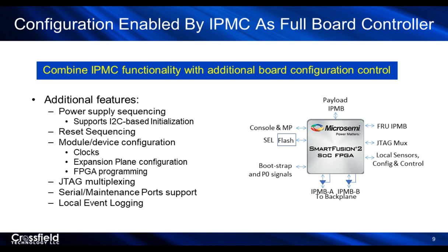And what I mean by the full board controller is, you would add things like power supply sequencing to an IPMC. A basic IPMC definition says you can start power supply sequencing, but you don't actually sequence each power supply as it comes up or deal with resets other than start and stop. Okay, a lot more depth has to be put into that device to enable it to do power supply and reset sequencing for the whole device.